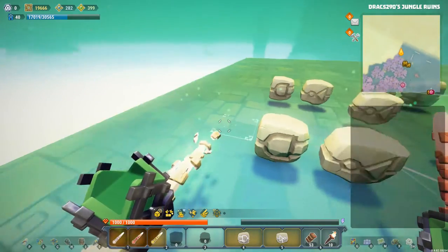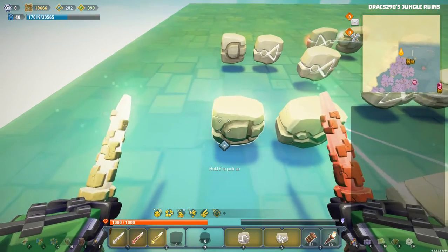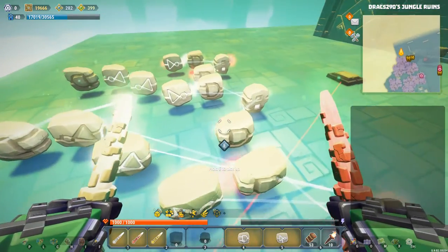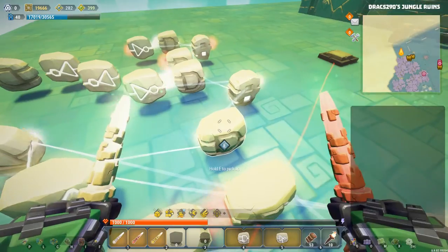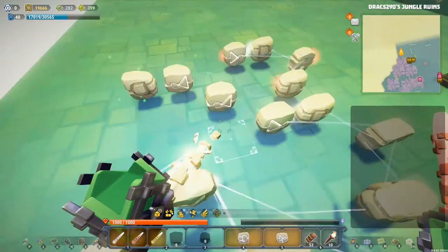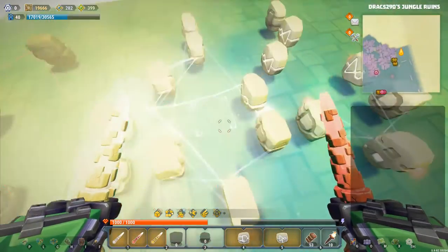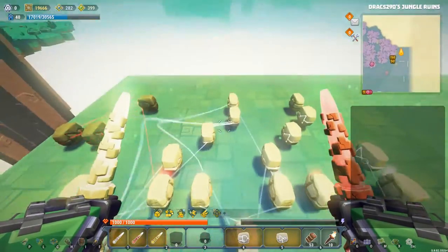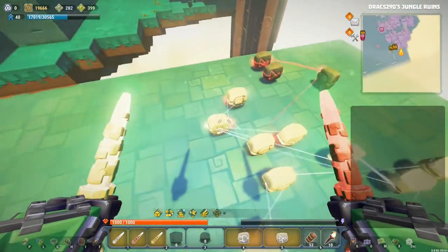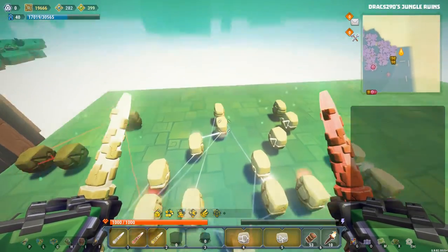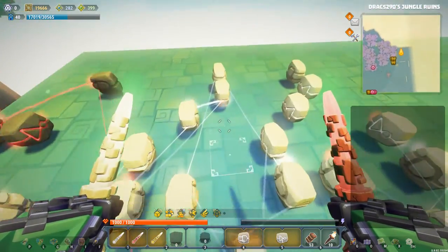That's good. Okay. So then we're going to run the AND gate up into the B side of this AND gate and the other AND gate as well. So these are the 2 AND gates in the second latch. That's the ones that we want to use. So there we go. So this guy is hooked up from first AND gate through the pulse into the second AND gate. That's exactly what we want to see.